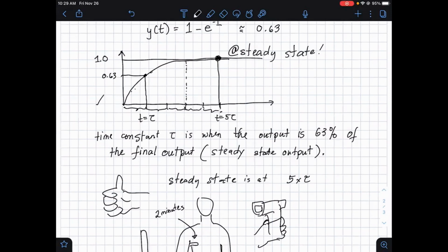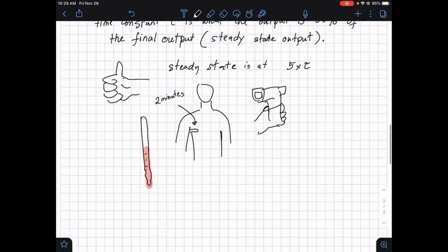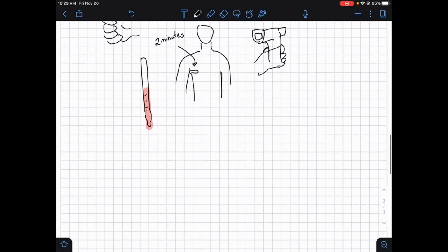You can also measure this yourself, okay? Again, by introducing an input, which is a step function. So you will measure it yourself. Also, one other way is by looking at first principles. A first order system can be described as this. In terms of the Laplace transform, a first order system has a description or a function given by this.